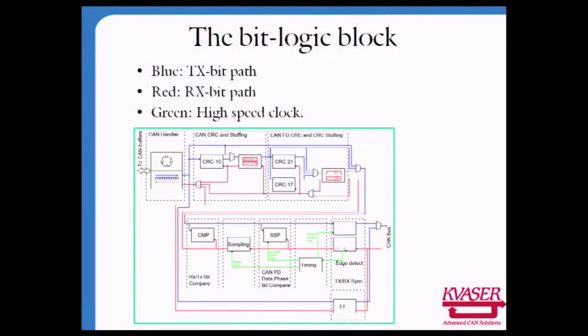This is the basic core of it. The first part you see there is the CAN handler. It goes to the CRC generation 15, and then you see one part that has been added here to handle CAN FD. So only 2 parts are included for CAN FD, the CRC generation and the secondary sampling point, marked with CAN FD.